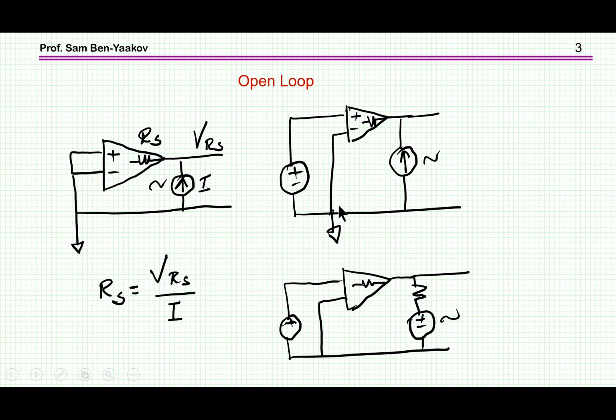This could be done if the amplifier does not have a noise model in it, because if there is a noise model, then this is going to be very, very noisy. So in case you don't have noise, you can, by simulation, stabilize the amplifier and then inject the current either directly or through a resistor and measure the impedance just by Ohm's law.